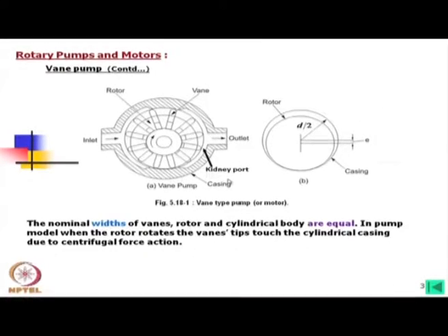So, this is the basic feature of vane pumps. In case of vane motors, this will be just opposite. This means that oil comes in at high pressure and goes out, and the torque is transmitted to the shaft.